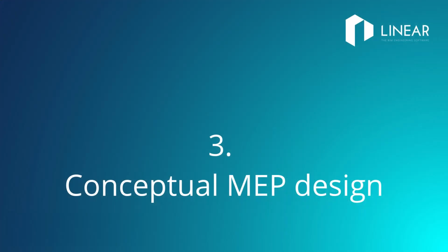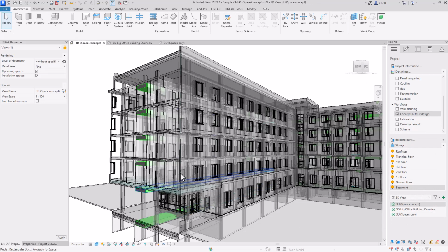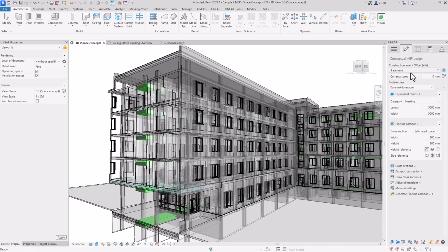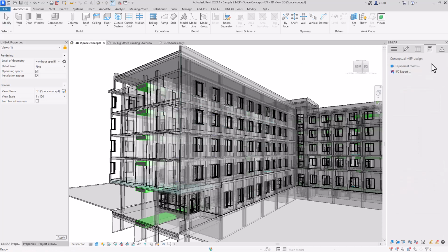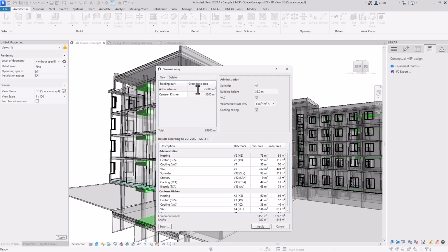At the same time, the position and size of equipment rooms and the supply routes can already be designed. The first draft of the pipe routes for the technical systems can be coordinated with the construction planners at an early stage in a BIM project. Areas can be reserved here with placeholders without detailed piping or air ducts. The sizes of these areas can be estimated with sufficient accuracy at this stage of planning.